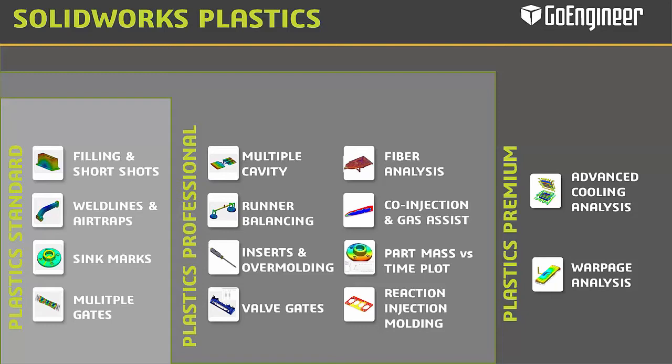Plastics Standard was designed particularly for part designers. It will answer the basic questions: will my part fill, where are the weld lines, and will there be air traps? It will help determine the best gate locations and optimize part designs for manufacturing.